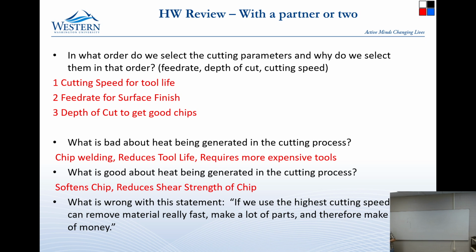Just a normal half-inch end mill used to be between $40 and, I don't know, $80. It depends on whether you get them coated or not. But if you start burning through these things very fast, they get really expensive. The ones that cut honeycomb cost between $250 and $1,200 a piece, and they burn out in about 2 hours. So they have a very short tool life, less than if you were cutting steel of the same thickness.